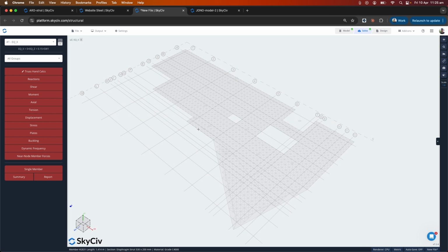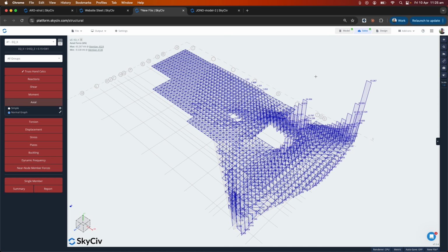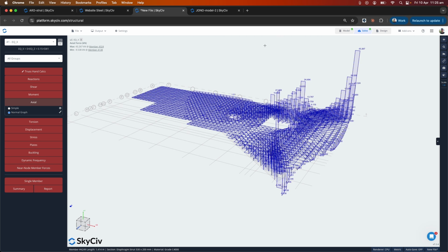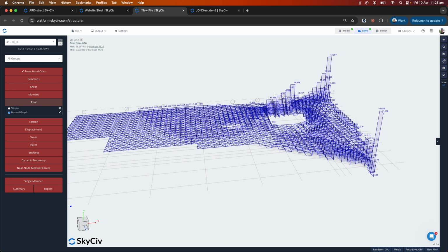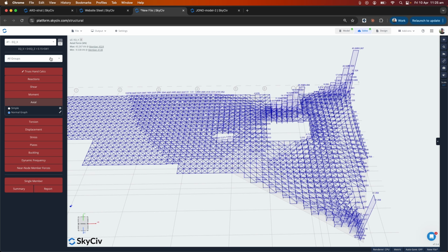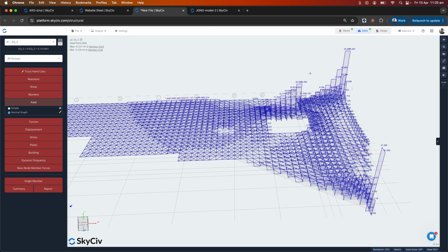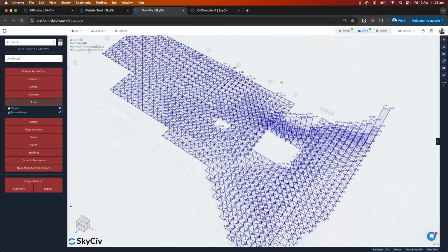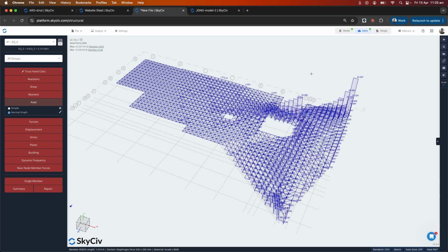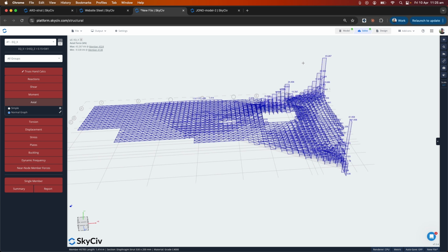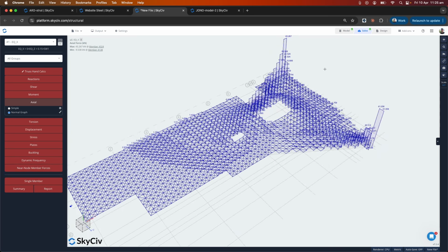Okay, so some members have been removed because they're tension compression only. Sorry, and let's have a look at some axial results. So obviously, it definitely matters where you put your restraints, but just to sort of show you some of the results that you will receive, and you can see some of the axial loads within those members. You can create groupings as well. So combining this with groupings, you can then group the struts into one group and the ties into another, so you can sort of isolate those results. But I can see some of the results coming through from my strut and tie analysis.